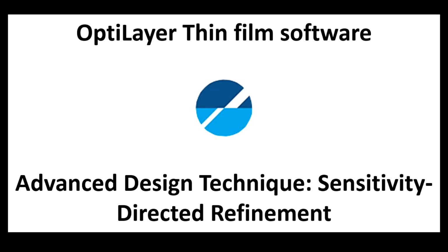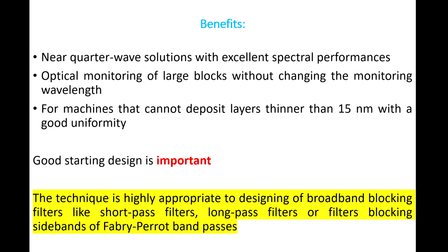In this video example, we would like to present an advanced design technique of OptiLayer software. It's called sensitivity-directed refinement. This technique allows us to obtain near quarter wave solutions with excellent spectral performances. These solutions are suitable mainly for monochromatic optical monitoring because it's possible to monitor large blocks of layers without changing the monitoring wavelength. This technique is good for machines that cannot deposit layers thinner than 15 nanometers with a good uniformity.